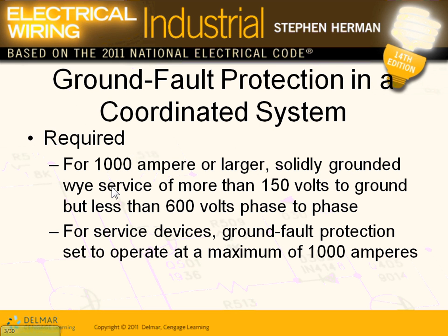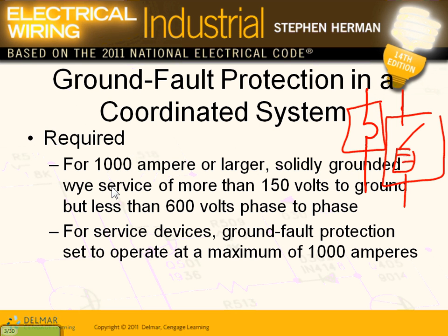So for the overcurrent protection device, we have either a circuit breaker or a fuse, as you have seen all the time. Fuses and circuit breakers. Here's a fuse. Every time you have a fuse, you always have a disconnect with the fuse, because the fuse cannot be used as a disconnect for the most part. You have to be able to isolate it. So these are the two devices that we're going to have, either a fused disconnect or a circuit breaker.